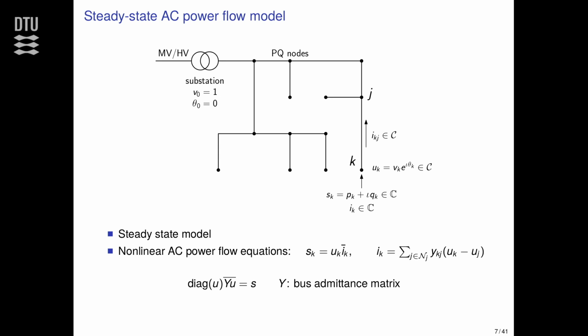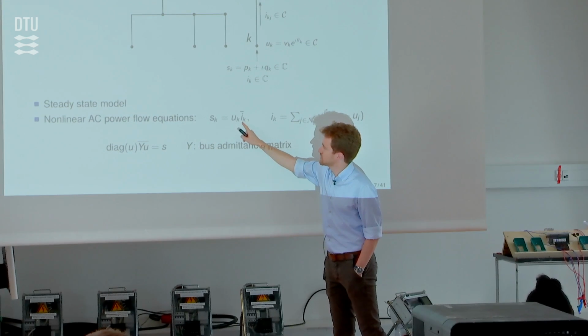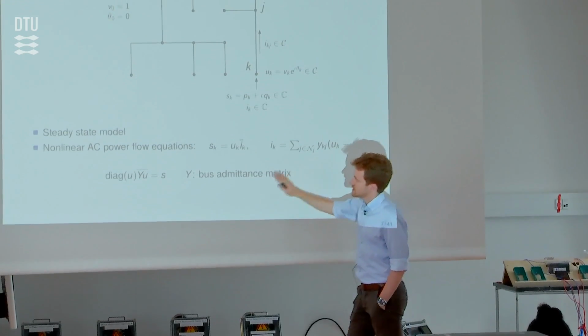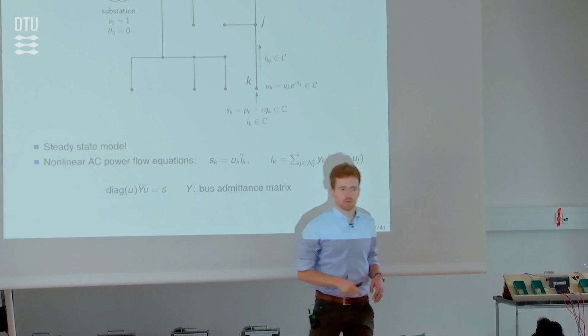The current on a node would have to sum to 0 for conservation of current. Complex power is the product between voltage and the complex conjugate of the current. You put this together, and you have a matrix form of the power flow equations.